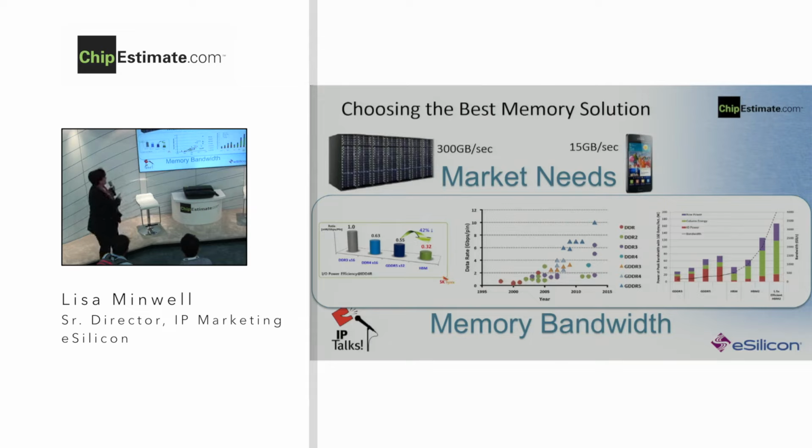If you look at the chart on the left, this is courtesy of SK Hynix, but it shows you the DDR3 going to GDDR5 and then going into HBM technology, and you can see this is showing you the milliwatts per gigabits per second per pin. So you can see that the advanced technologies, as you get into more of a stacking memory, are really beneficial.